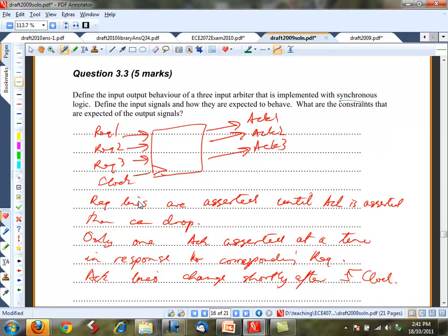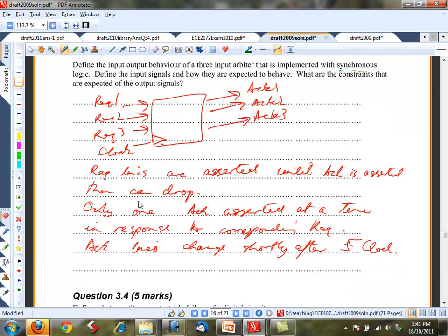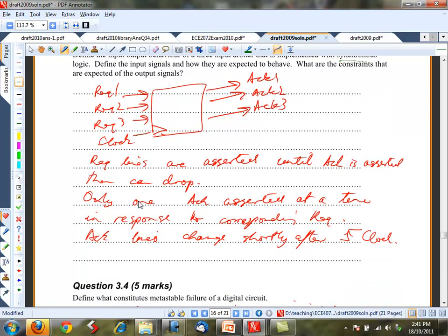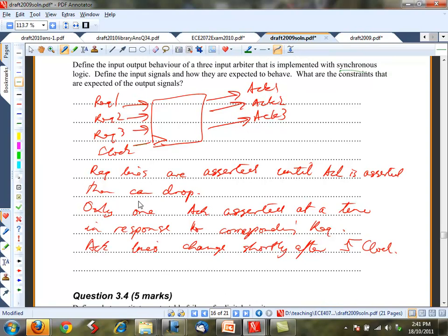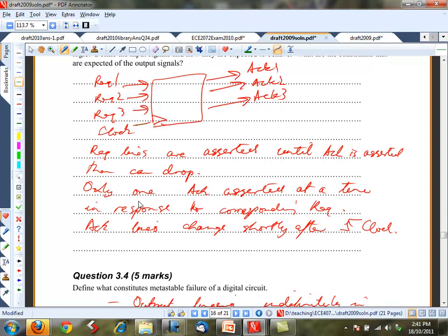Now, I think Freddie would have gone over an example of how that works in practice with a timing diagram. Remember that? So that is embedded in that timing diagram. You need to be mindful of that protocol where you can't drop a request until you've got the acknowledge. So you should be able to draw a timing diagram for each of those different protocols of arbitration policies.